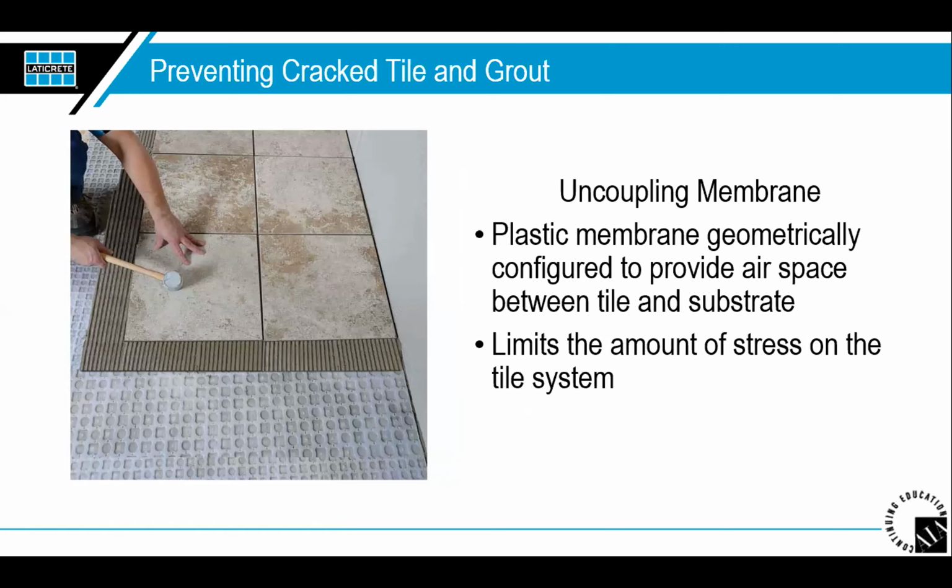This is becoming more and more popular versus using the concrete board on the floors itself. So this is going to be used on a floor installation only, right? It limits the amount of stress on the tile system. And what it is, it's a plastic membrane that's configured to provide airspace between tile and the substrate. So same situation as what we were talking about.